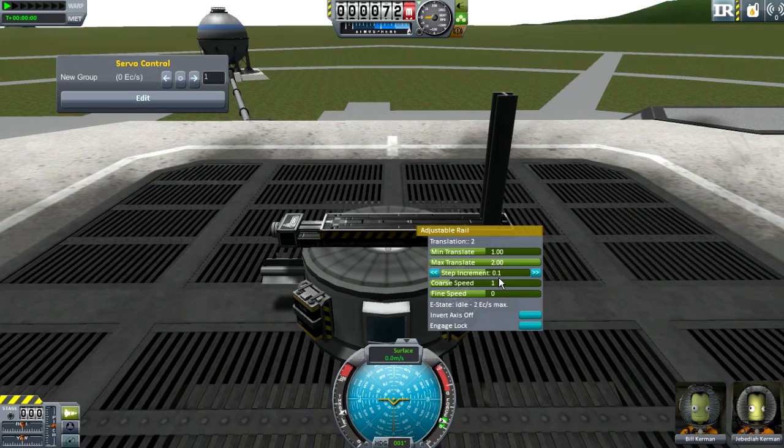If we tone it down to 0.1, then you can see now we have 1.4, 1.5, 1.6, 1.7, and so forth. It goes by step increments of 0.1. And 0.01, you can see now we can get even more precise increments. So this is a tool to help you edit the translation amounts. Now if you get them set to uneven values, such as this, 0.37 and 1.44, then you can go back to step increments of 1 and it will reset into the 0.1 settings field.